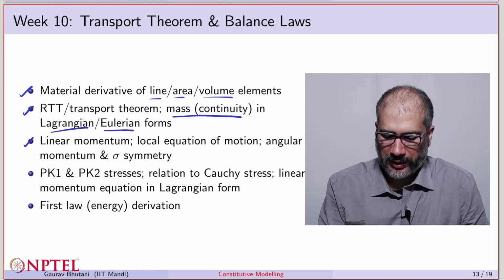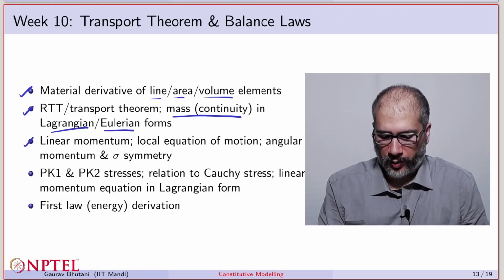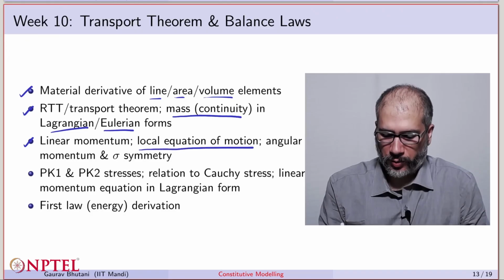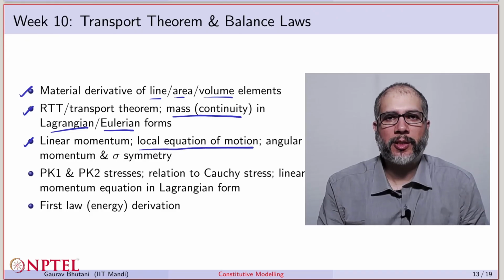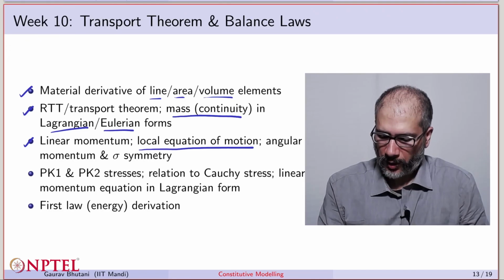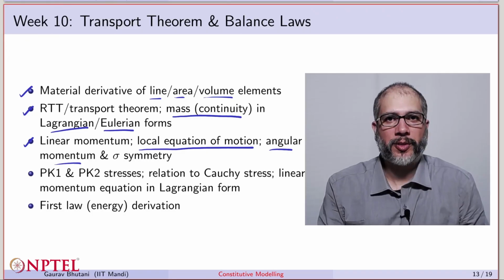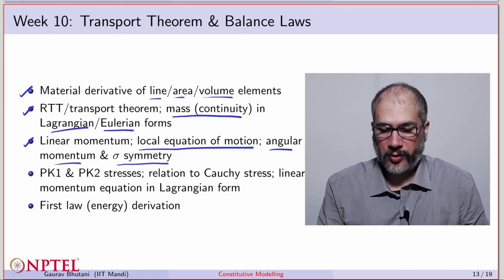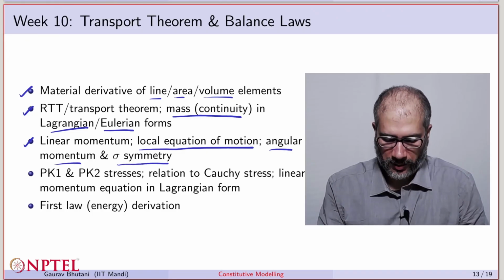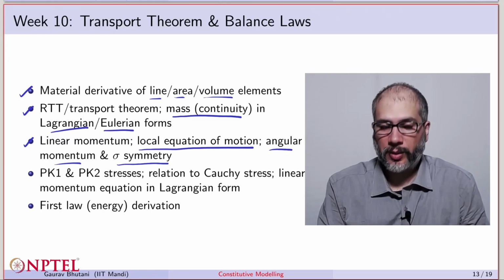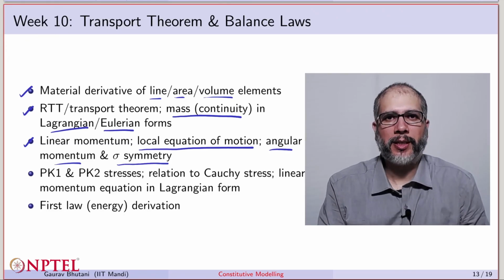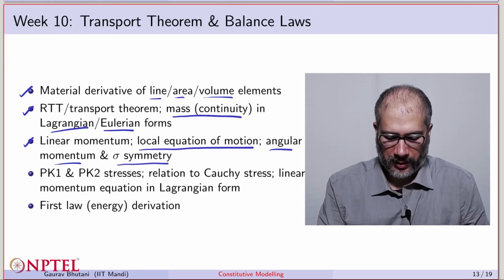We then moved on to the linear momentum equation, which helped us write the local equations of motion. And this time the equations are not for equilibrium, but for a general situation where the continuum may be accelerating. We also applied the ideas of angular momentum and demonstrated the symmetry of sigma again, but for situations where the system may be accelerating.